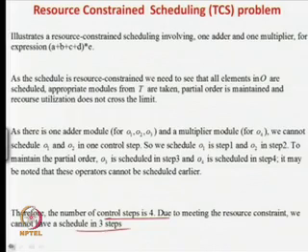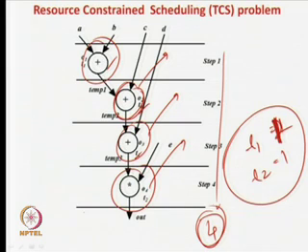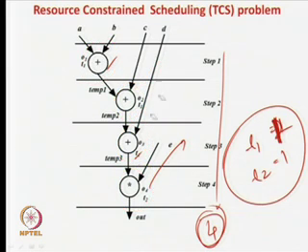In this case it was only about the resource constraint. So, the designer is saying that T1 equal to 1 and T2 equal to 1, that is maximum 1 adder and maximum 1 multiplier. So, you require 4 steps. Okay, so, it is one more than the case when the constraint may be 2, that is 2 adders kind of a thing. So, we have increased from 3 to 4.